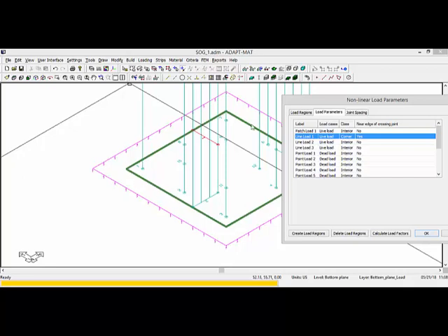So we're only designing this panel in particular, but a portion of that load, because there's a joint there, will be transferred to the adjacent panel. Now we just accidentally selected a line load. That's fine. We can relabel this. I'll call this an edge line load. I should have been down here at a point load, and we'll call that a corner load.